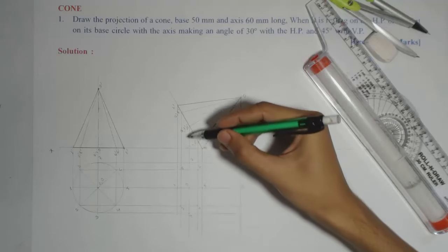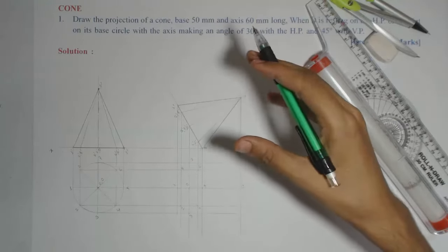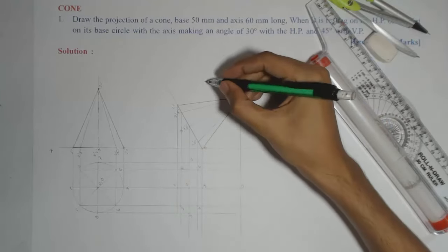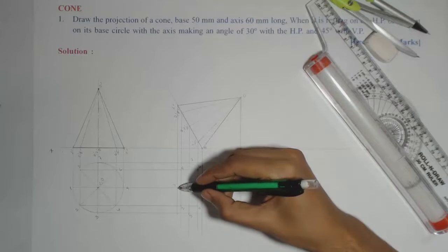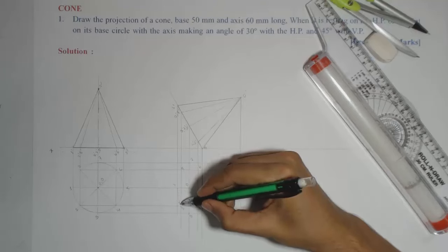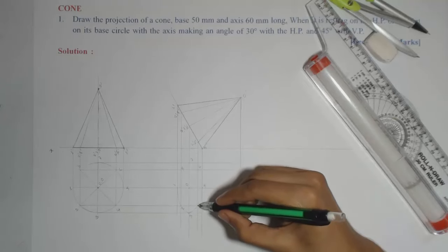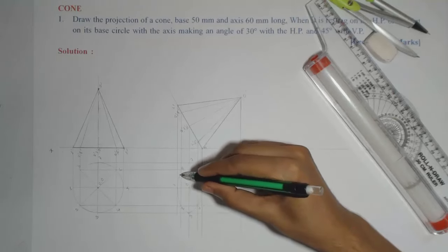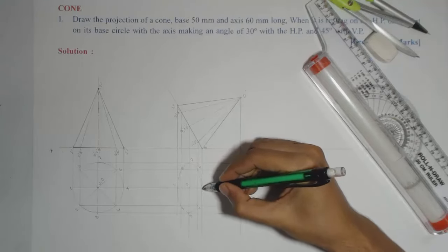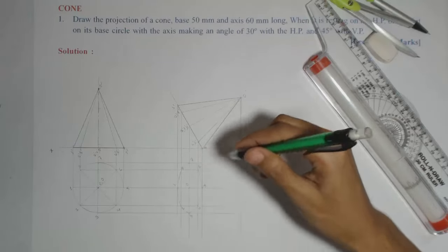Now for cone, this base which is appearing a straight line in this view is nothing but a circular base, but after tilting from top view it will appear as an ellipse. Now first I'll join all the points on the circle 1 to 8 by smooth light line. So I should get a shape of an ellipse. Then after doing this, I'll decide which part to make dark and which to keep dotted.